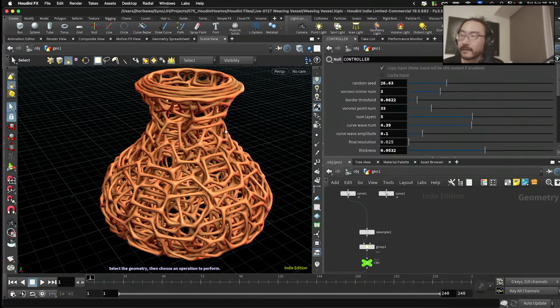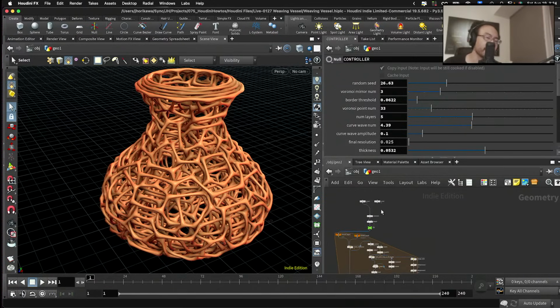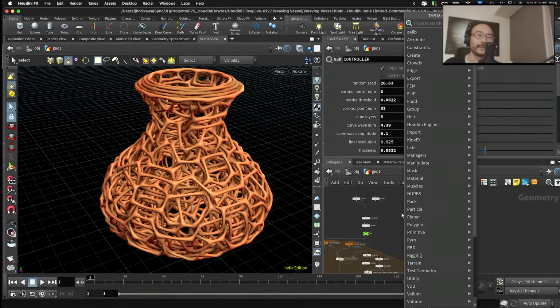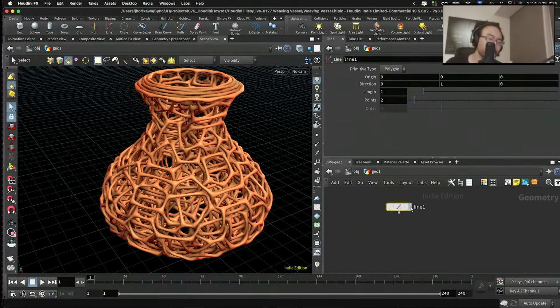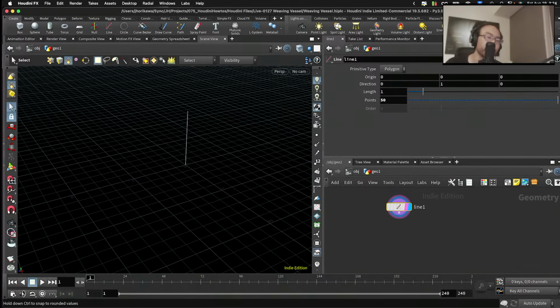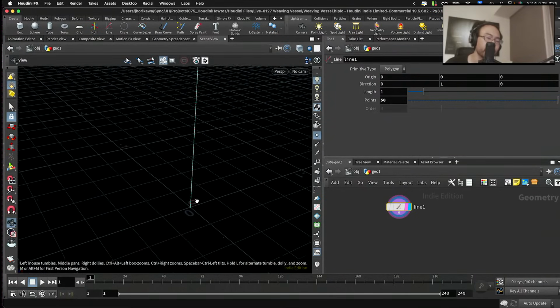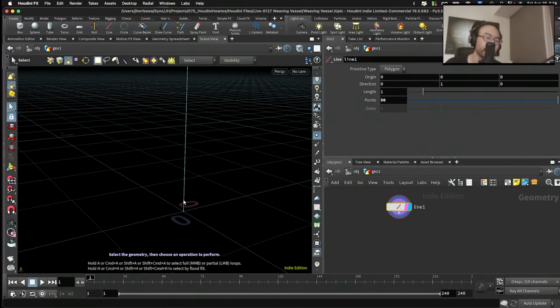Delete. I see. How to delete every second geometry with VEX? Every second geometry, is it related to this one or not? In general, if you want to delete every second geometry or every second point, you could just use modulus. For example, if you have a bunch of points like that, and you want to delete every second point on this line,